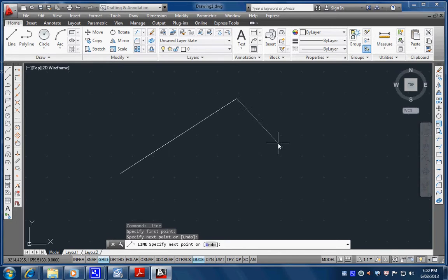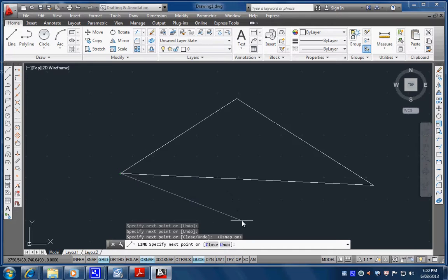Because it's a vector, it does recognize certain things. If I turn my object snap on, it recognizes, for example, the endpoint of that. And if it's not available, I can click it, the midpoint, and there's a midpoint. There is no midpoint. I can make it go there by clicking this, and that's an accurate position. More about that later. Enter to finish the command, or escape.